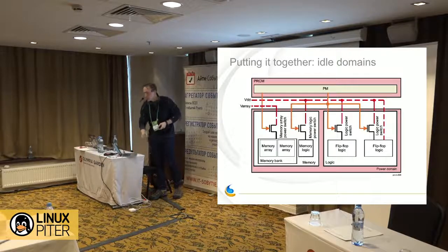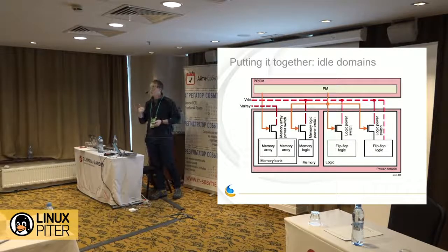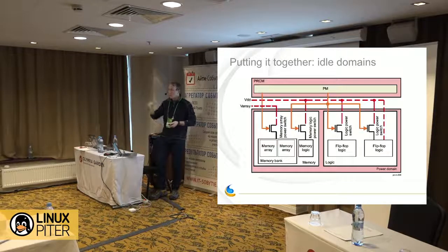These idle domains may just be simple on and off semantics. It's got power or it's totally power clamped. But you'll also see schemes where there are intermediate levels of power savings. And I mentioned earlier, for instance, lowering the voltage quite a bit to do a little bit of memory retention is a common one that you'll see.